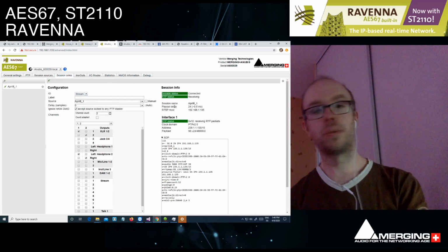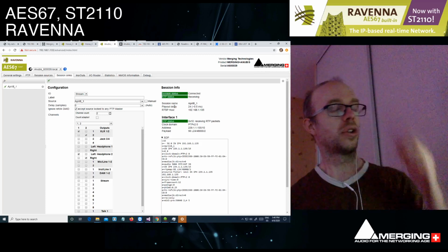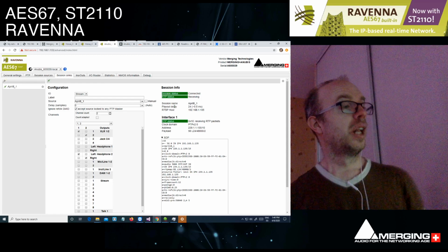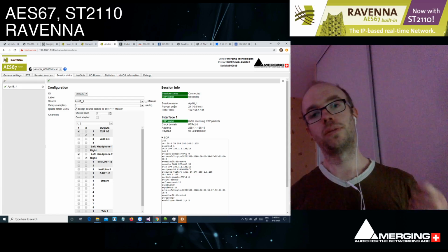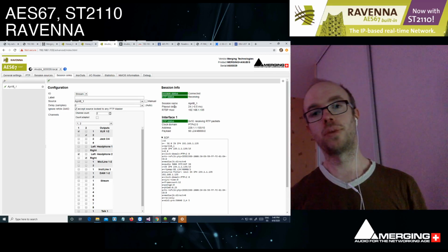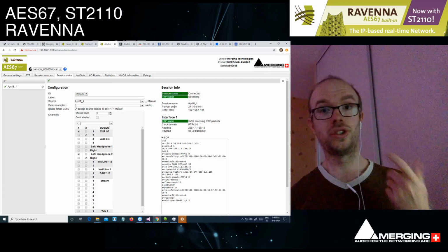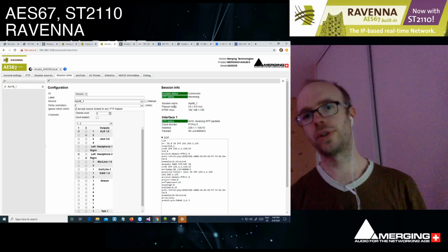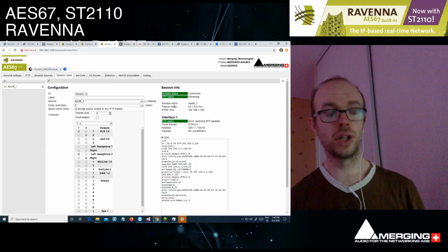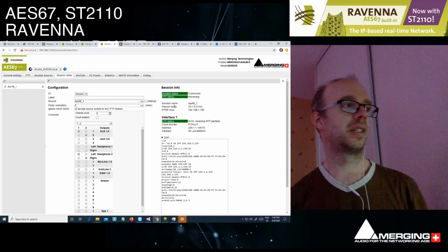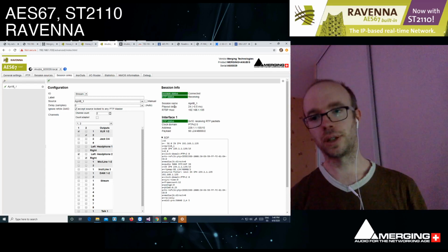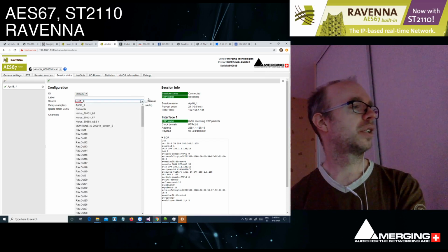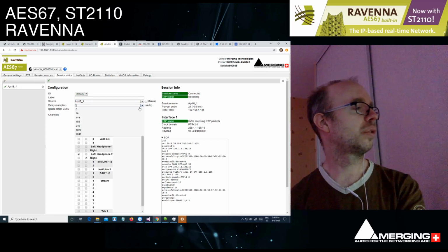So this is the player delay, and the player delay is the buffer on which I will put the different packets when I get them from the network. So the bigger the buffer is, the better my receiver is able to cope with different changes on the network, so jitter or longer path, etc. So for instance, we have customers that do transatlantic or transcontinental AES67 connections. Those connections will not be made transporting the data in less than a millisecond. So we have buffers that can go higher than 100 milliseconds.